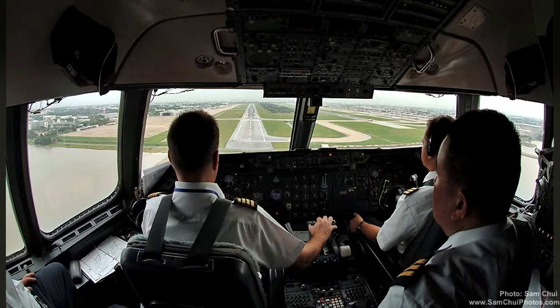Until standalone GNSS precision approaches are fully developed, a precision approach will probably mean an ILS approach, and in this instance the final approach segment begins at the FAP. You should recall that this is the point in space on the centre line of the localizer specified for the final approach track, where the intermediate approach altitude or height intersects the nominal glide path.